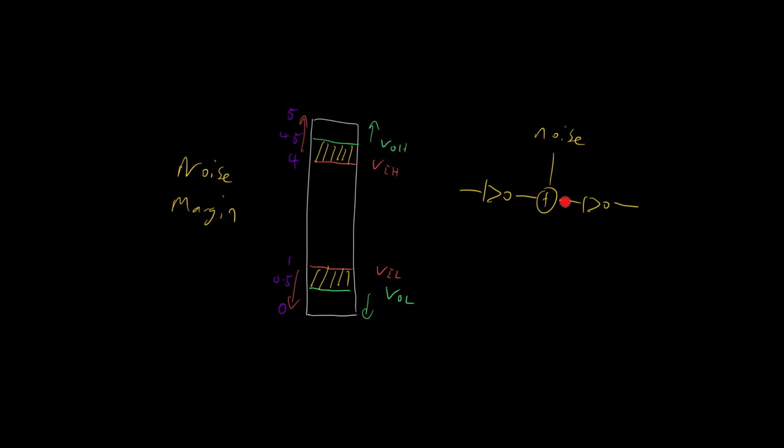So even if we had noise of half a volt riding on the input here, we get rid of that at the output here. Every single logic gate is cleaning up the signal, which means digital systems are very robust to noise. Basically, this is why we switched over from analog computing to digital computing. In analog computing, the noise just causes too many problems. Digital computing, you essentially get rid of the noise problem completely.